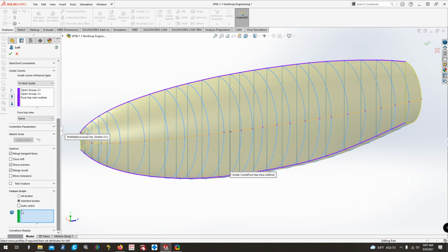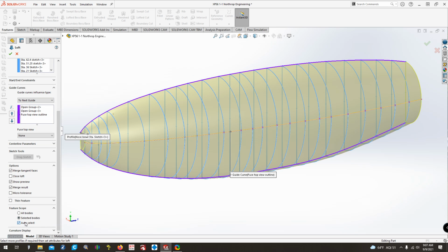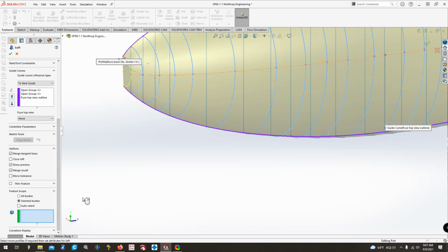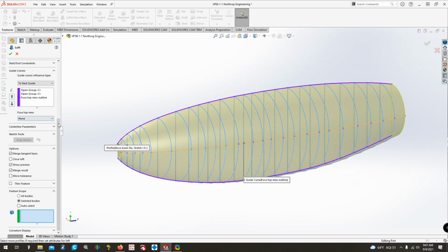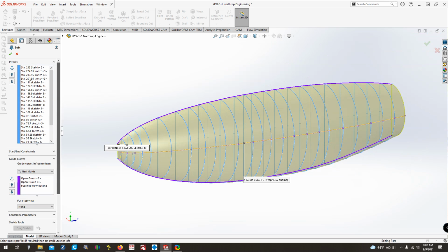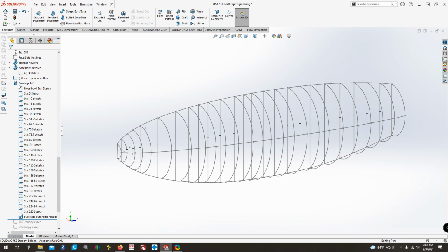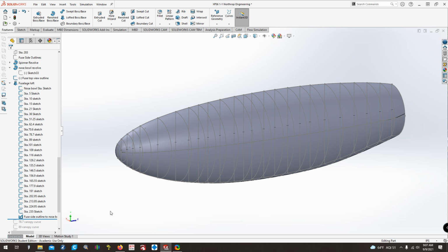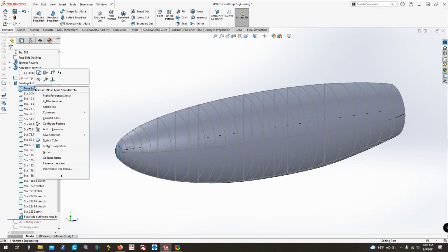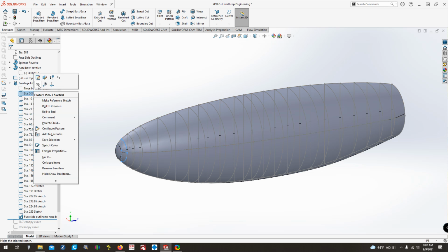to where you would select automatically or manually by undoing the select box, and you can merge two solid bodies. In this case, we don't need to worry about any of that stuff. So we'll just have it like this, and you come up here and you would click on the green check button. In this case, I've already done it, so I'm not going to worry about it. I'm just going to unhide the part. And now what we can do is we can come down through here and we can hide a lot of these